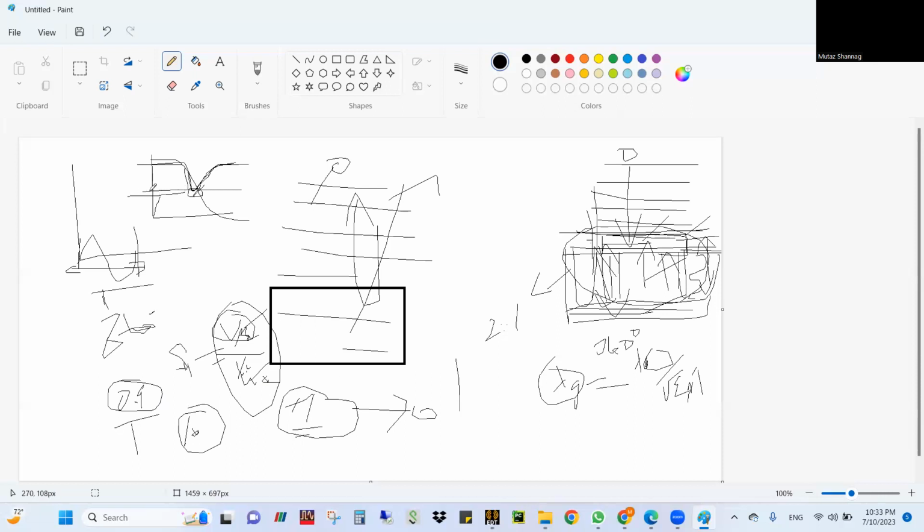And this phase, right? Whenever you see the resonance, it is a kind of zero crossing. Zero crossing means where you see resonance, the reactance effect is nullified, right? When reactance is not there, you see the resistance alone, and resistance means zero phase.